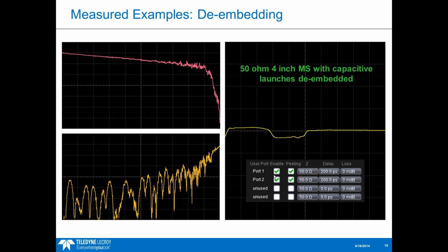This makes it really easy, almost trivial, to do that de-embedding, rather than having to design a special cal kit or do manipulations of different S parameters. You just punch in the values and press recalculate, and as you can see, it works pretty well here. That's typically what I recommend for people who have the Spark. Otherwise, there's a lot of information out there about de-embedding fixtures and different ways to do that.